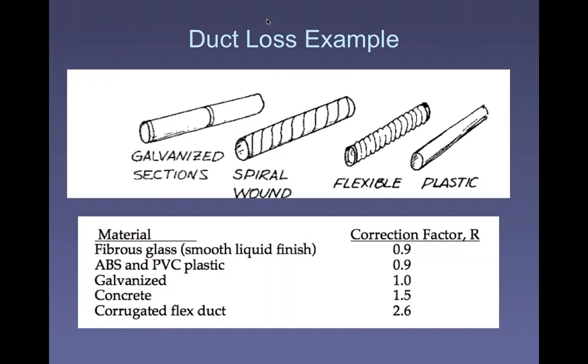What you're losing through a length of ductwork is a friction loss. We probably will phrase them in terms of the source of the loss, like duct loss, elbow loss, or hood entry loss, and so on. Friction loss is a pressure unit. It's inches of water, which is pressure, or millimeters of water, whereas K is unitless.